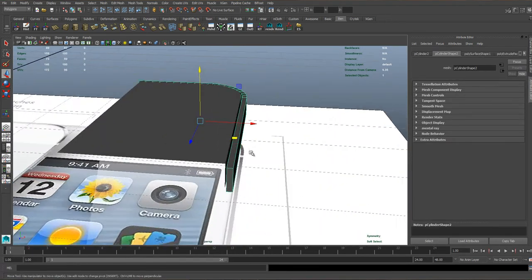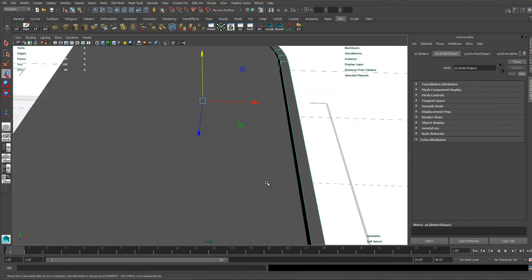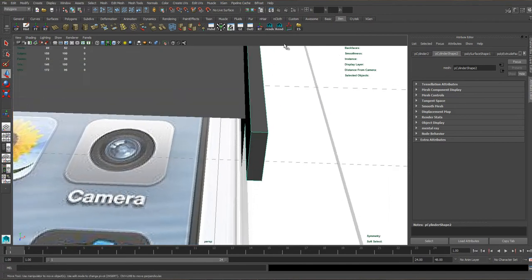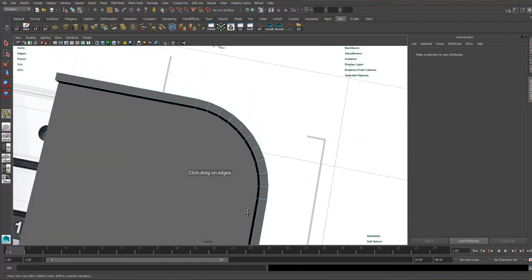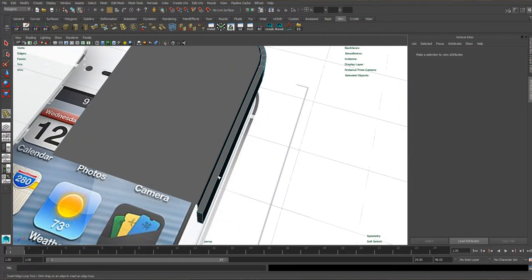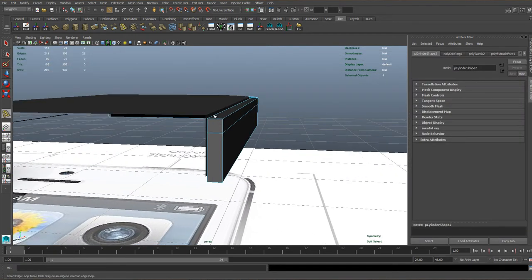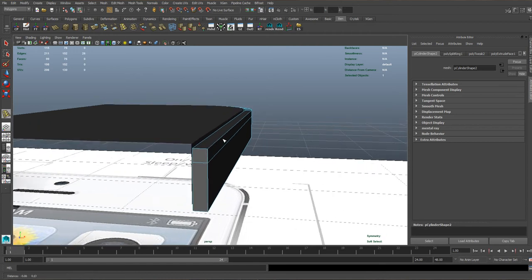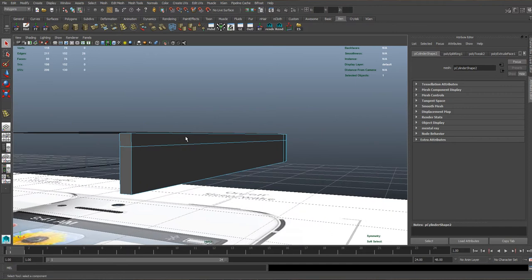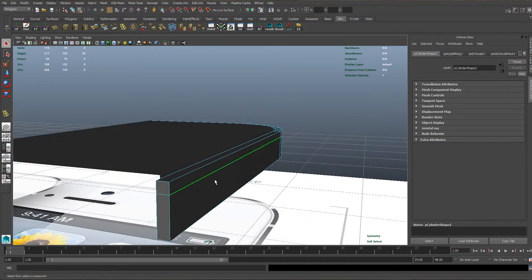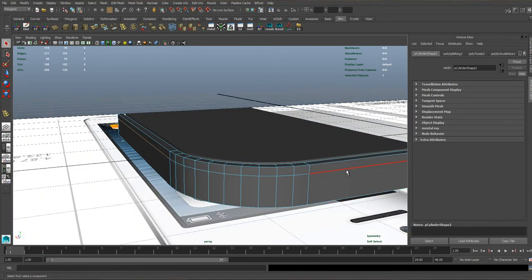Okay, so next we're going to go and add the bottom of this groove there. So we just need to add an edge loop to our outer metal piece of geometry, like this. I'm gonna keep it quite far down because we're gonna add a very big bevel to this outer edge, and I do not want to restrict that bevel by the time it gets to this edge here. So keep it far enough down. It could even be halfway down if you really wanted.